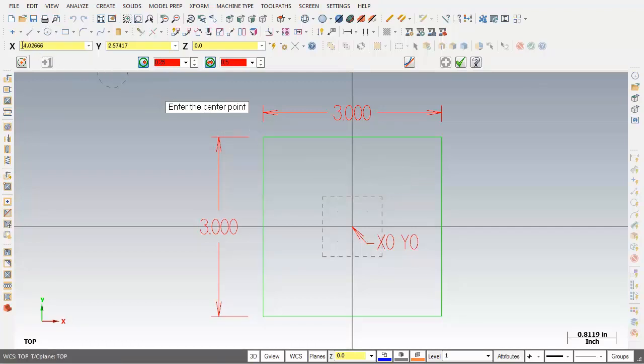So up on the AutoCursor, I'm going to click in the space for x and input 0.75. Going to hit the tab key, and now we're transported over to the y. I'm going to input 0.75. Going to tab over, and the z I'm just going to leave at 0. I'm going to hit enter now, and there's our first circle. Over on the right side of the ribbon bar, I'm going to click on apply.